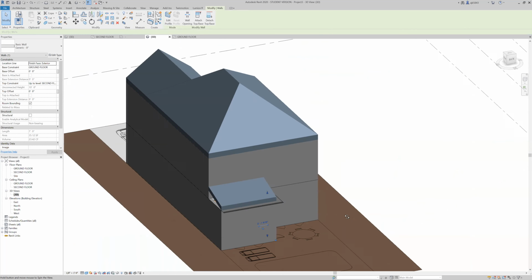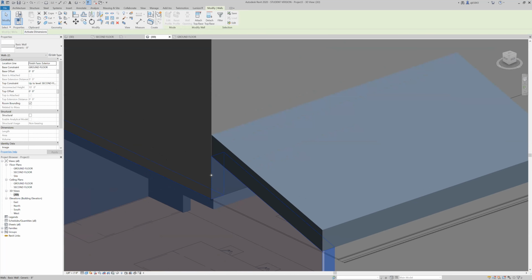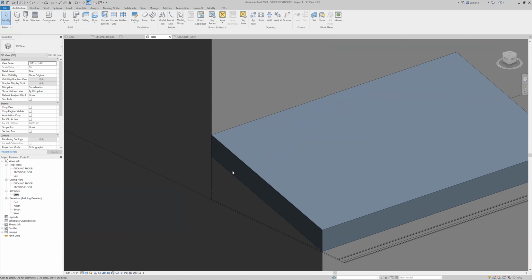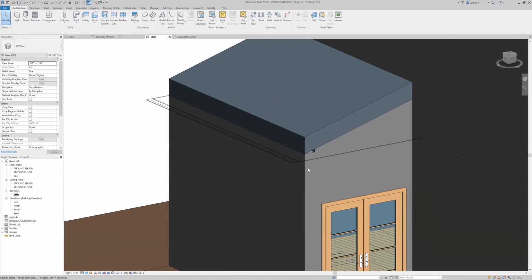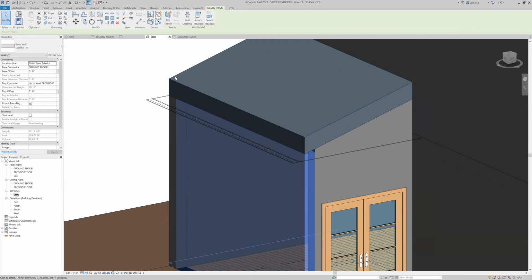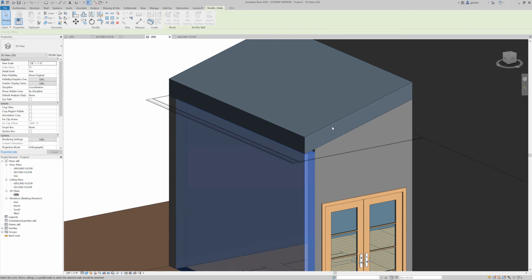And then I'll have these 2 walls. I should be able to attach them both to the roof. You'll notice it pulls up just the area that affects the roof, leaving the rest where it needs to be. And this one as well, since I have that small area there, go ahead and attach that to my roof as well.